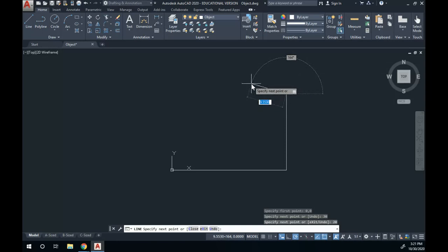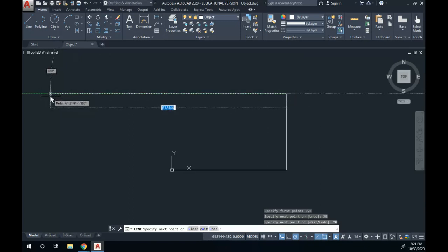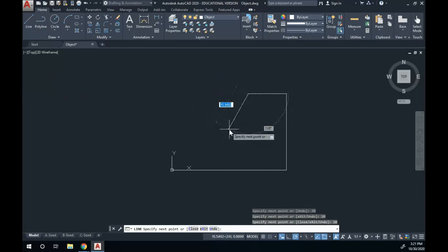Continue to draw the shape shown in figure 2-24 by moving the crosshairs in multiples of 90-degree angles and typing the distance for each segment. So I'm going to look at that picture in the textbook there. It says I'm supposed to go over 10 units to the left, and I could be way out here if I wanted to. It doesn't matter. I'll type 10, enter, and it makes it 10 units long. Let's go down 5. So as long as that green line's showing, I can type 5, enter. To the left, 10 units. Up, 5 units. To the left, 10 units.